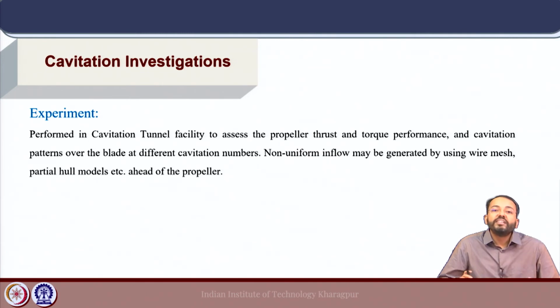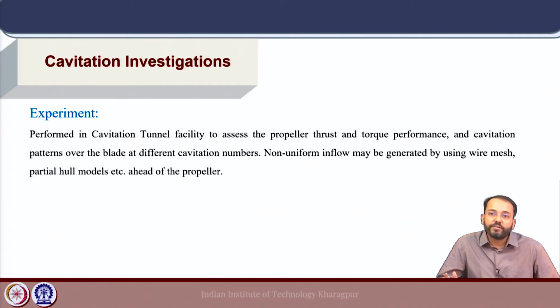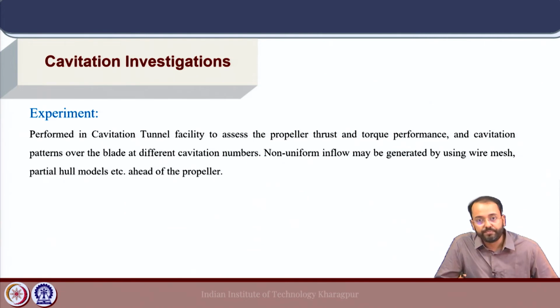Now, what are the standard ways of cavitation investigation on propeller blades? We have briefly covered the concept of cavitation tunnel under model tests. So, cavitation tests are done in cavitation tunnel facility where the propeller thrust and torque performance as well as cavitation patterns are studied at different cavitation numbers.